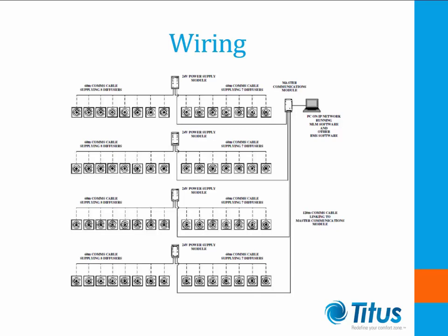Electronic VAV diffusers can be interconnected and scaled to make larger systems. Larger systems can be constructed by linking up to 15 individual diffusers or thermostats to one interface box and up to 4 interface boxes to one communications module. This means that one communications module can handle up to 60 diffusers. By connecting the communication module to a building-wide system, full transparency and control can be realized.